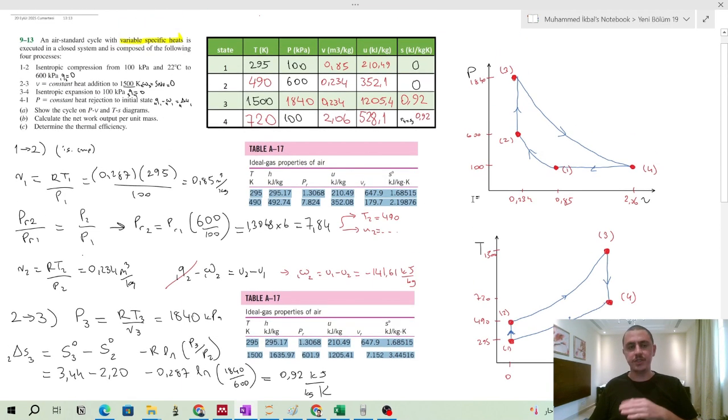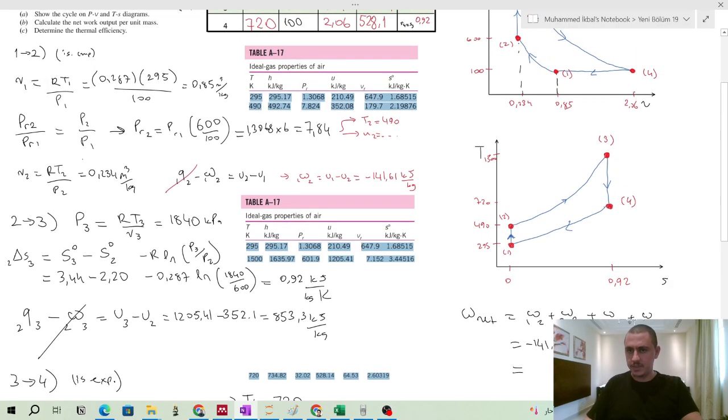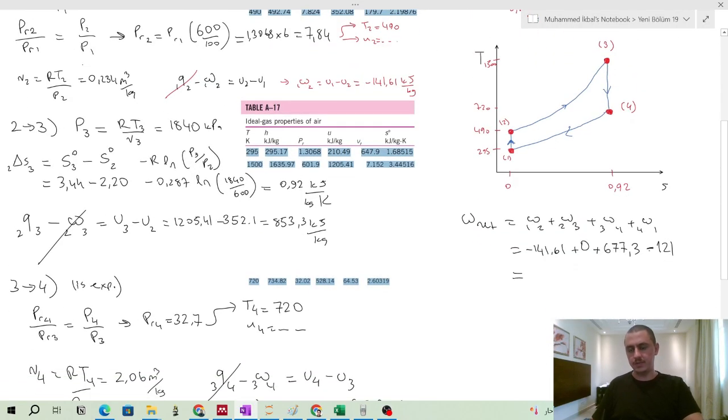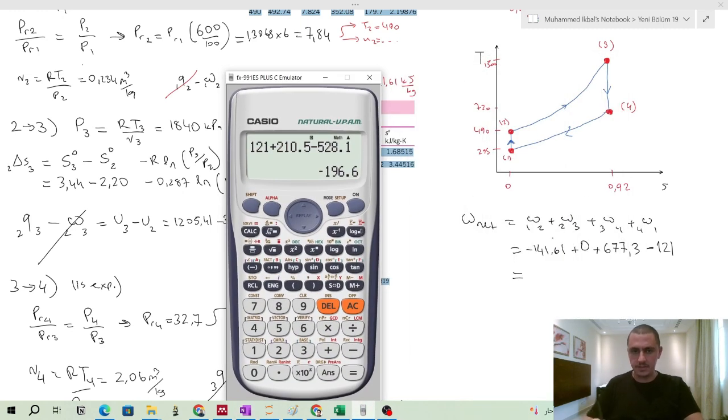It depends on the expansion or compression. Well, what's going on here? Let's see. From the PV diagram, we can understand the work. Is it input or output? Here you are going to negative, like you are going to left, so this is negative work. Okay, 4 to 1 also negative work. Because you are going back, you are decreasing the volume here, so you will get a negative sign. Okay, so sorry for the mistake here.